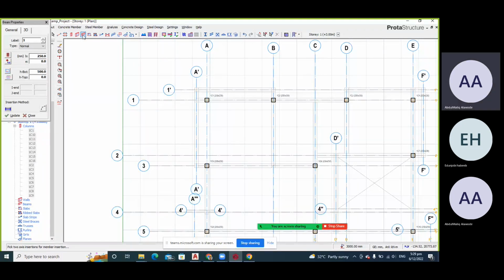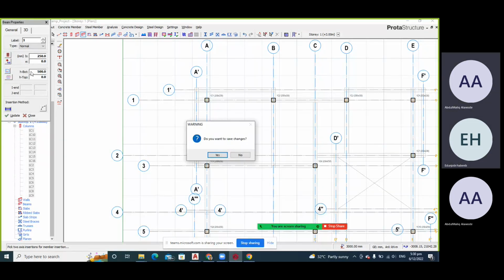Now the sizing of our beam, we are taking it as 230 by 450. I think I've explained in our previous classes the reason why most people go with 230 by 450. The 230, the width, is because most of our block wall is 225 to 230 thereabouts. Then the depth is within the range of provision that we have in the BS code.